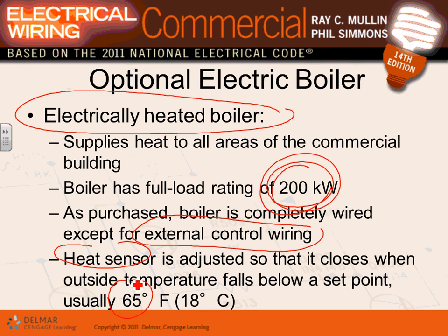Do you want to heat the building when it's 90 degrees outside? So this sensor will control the boiler externally first. Do I even want to start that baby or not, is it cold outside? Otherwise, the boiler is blind. It doesn't have any eyes, right? So you need to sense what's going on outside.